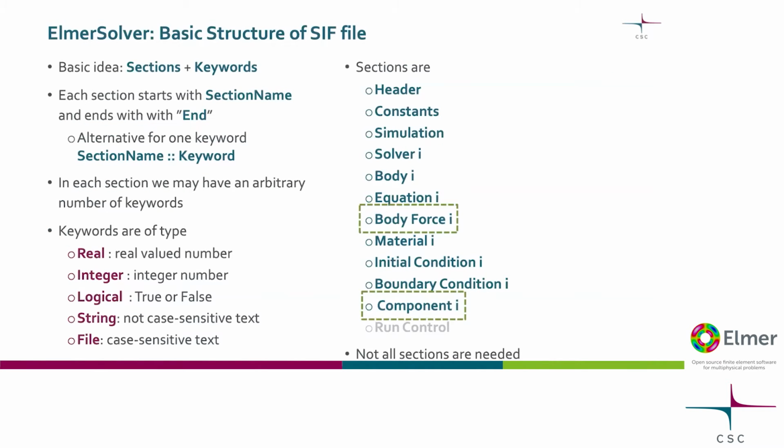Before we jump to the next slide, the CircuitBuilder will be focused on these two blocks, which are the body force, which, if you're an electrical engineer, you probably know as the external source. That's how we apply either a current or a voltage-driven problem. And then we have the component, which is what will allow us to couple the circuit to the finite element model.